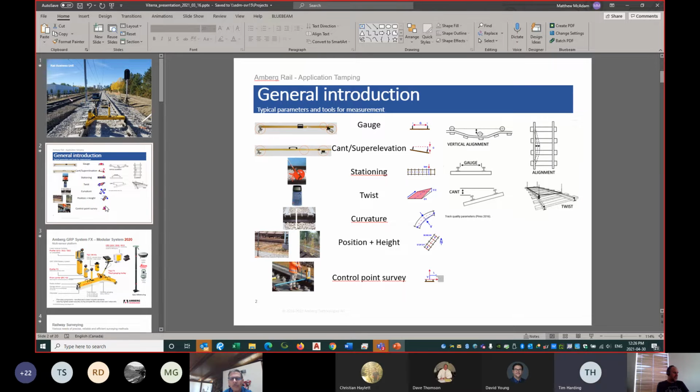The Guido was, from my understanding, built off of roads and road thinking, so the software doesn't deal with the spirals as well as the Amberg does. The Amberg actually creates a spiral, where the Guido will approximate it with line segments. So there is some loss of accuracy in doing it that way that we wouldn't experience with the Amberg.